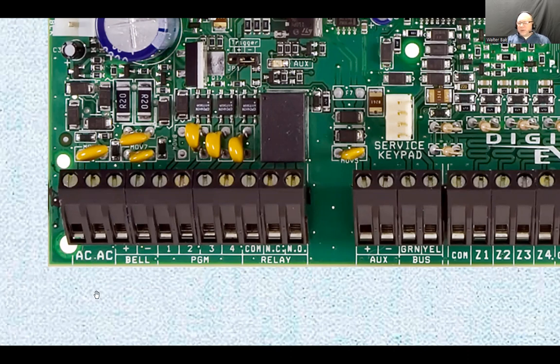The wire-in transformer also looks like the doorbell transformer. It fits a knockout in the electrical panel, so you can mount it right onto the electrical panel and wire it in with a designated circuit breaker for that. And on the other side, there are a couple of screw terminals that you could use to power up this AC. So between here and here, you would have something like 18 volts AC.